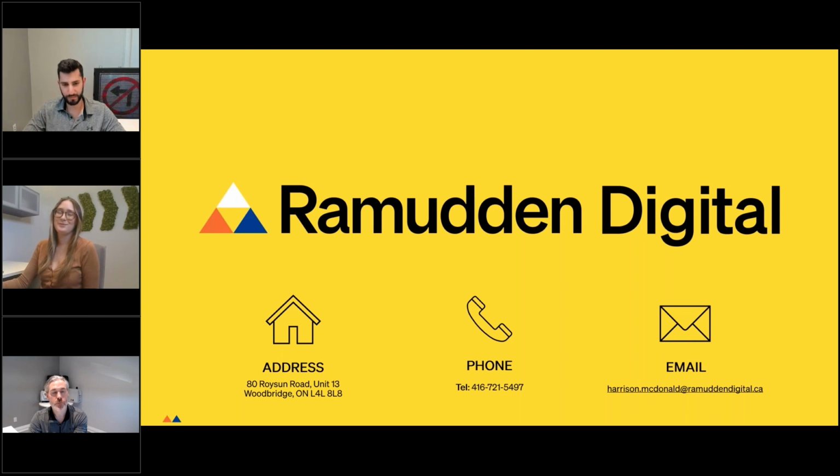Yeah, you can mount these on a signal arm or the vertical portion of the pole. We would advise mounting it closer to the pole if you're going on the signal arm, just to balance the weight a little bit better. Just for reference, this sign behind me is 30 kilograms. We supply it with a can bracket, and that can be mounted on the signal arm or the vertical pole. But of course, you've got to do your own structural analysis on the type of poles you use.